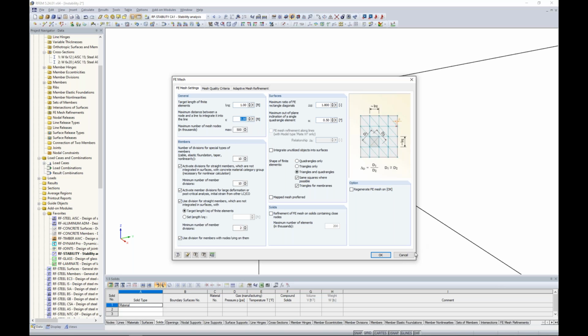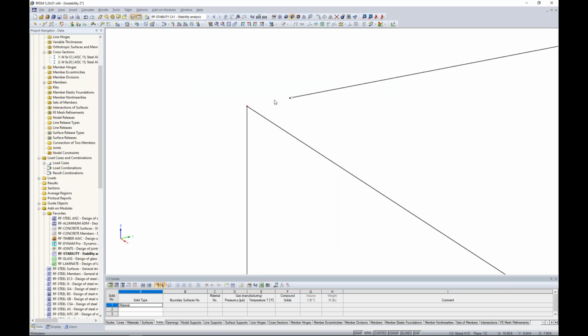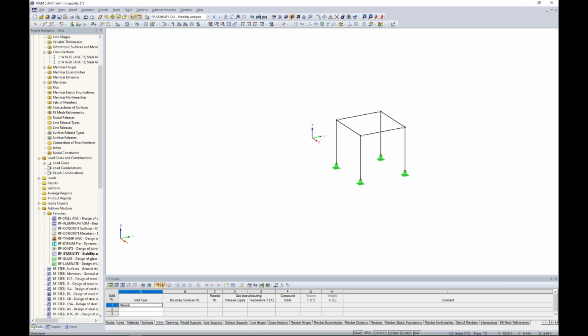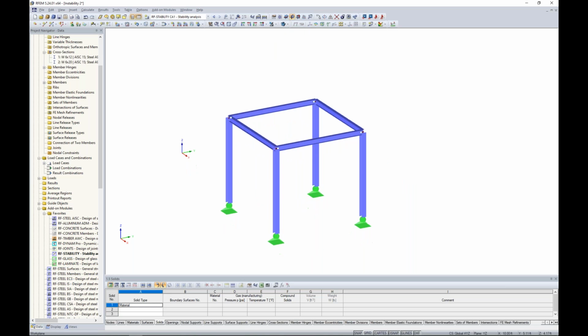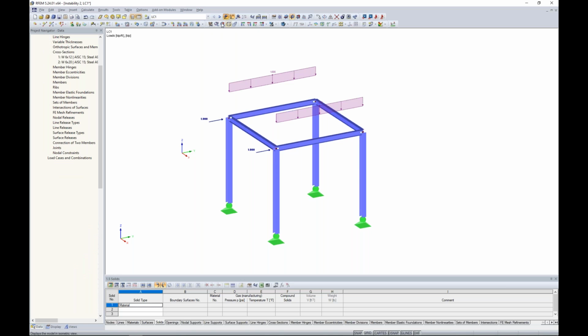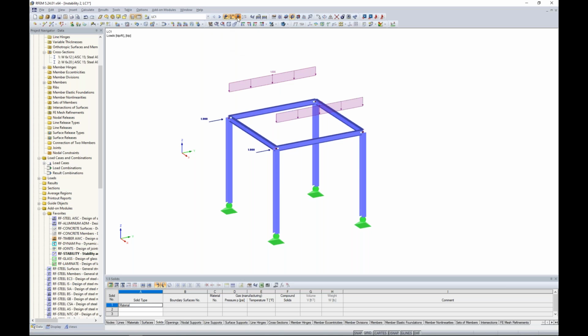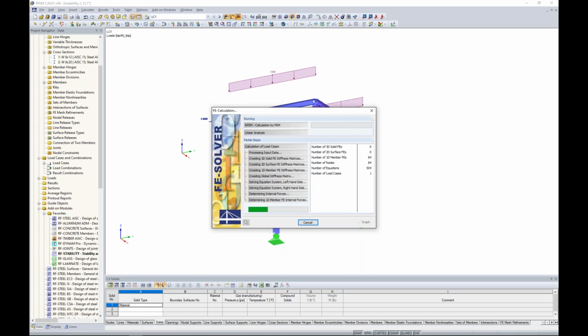So we'll leave this as default, because clearly this distance is much greater than 0.003 feet, and all we need to do here is grab this node and snap it to that column. Okay, so hopefully we've alleviated this instability. What we would do now is jump back to load case 1, remember with those same applied loads, and we'll begin to run the calculation.